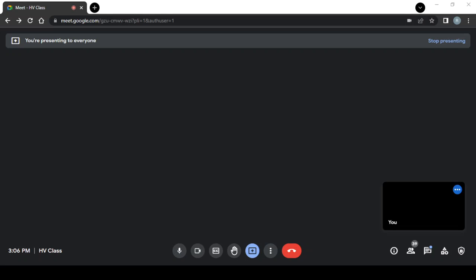And then it is quite convenient, and the limitation is that it requires calibration. Of course, all the probes would require calibration and careful construction. A disturbance in the position mounting of the electrodes makes the calibration invalid, because this one we are dealing with electrostatics, and the calibration is quite tricky, and this one involves several electrodes that will cause a kind of discrepancy to the values.